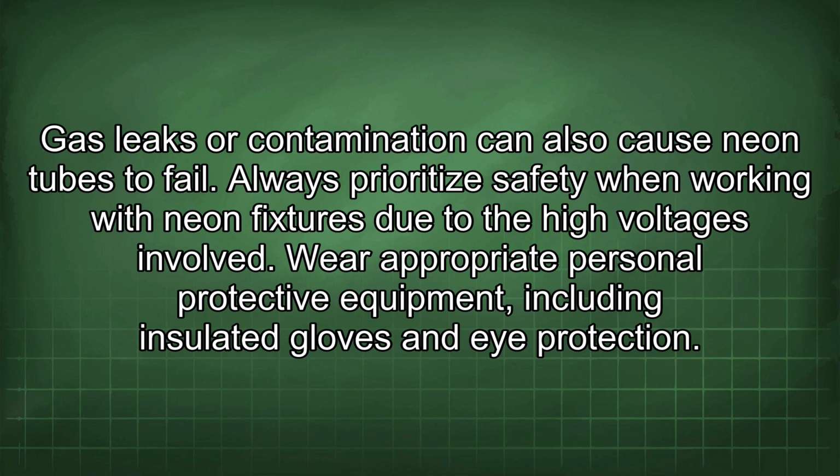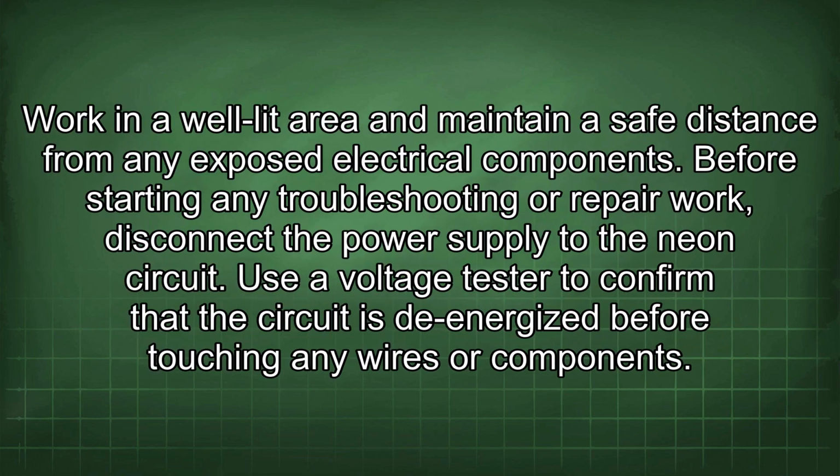Always prioritize safety when working with neon fixtures due to the high voltages involved. Wear appropriate personal protective equipment, including insulated gloves and eye protection. Work in a well-lit area and maintain a safe distance from any exposed electrical components.